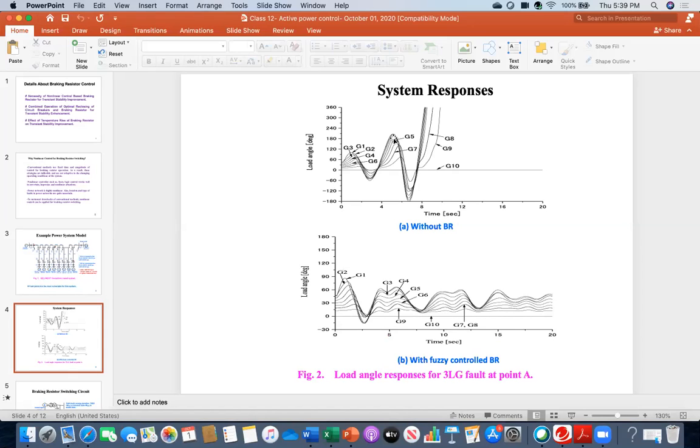And then again it started, much overshoot, downside much overshoot, next stage much more overshoot. I mean, growing oscillation, a fully unstable situation, lack of synchronization. This means fully out of step. So that's why it is called vulnerable. And it is not just one or two generators, all of the generators went out of step.